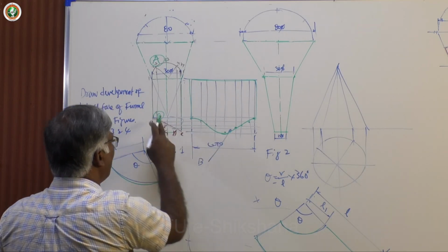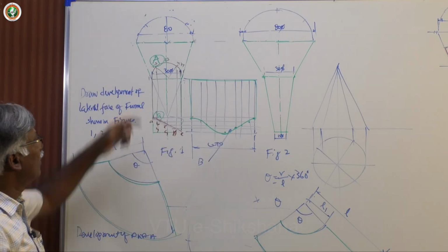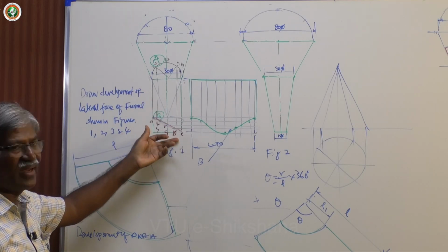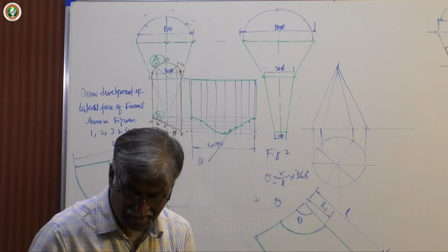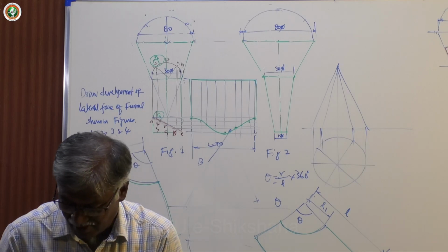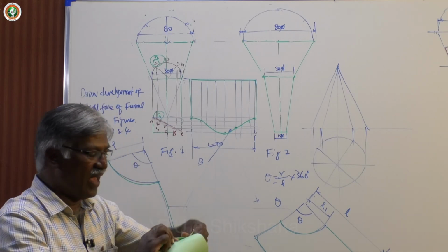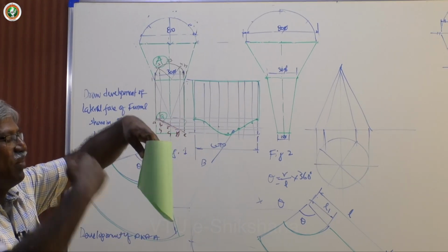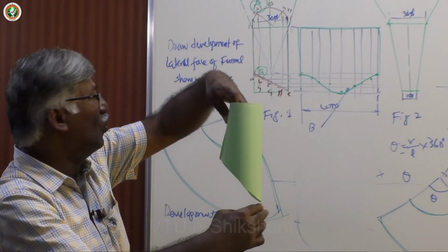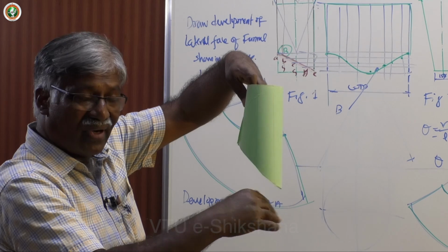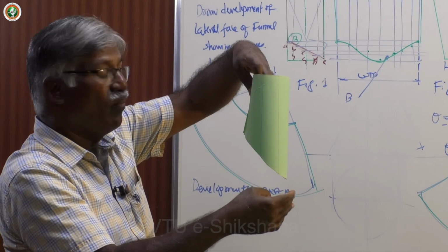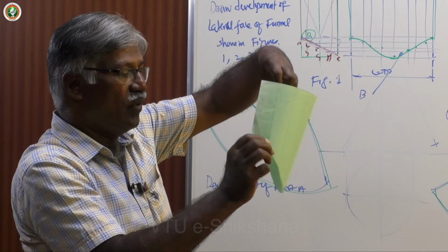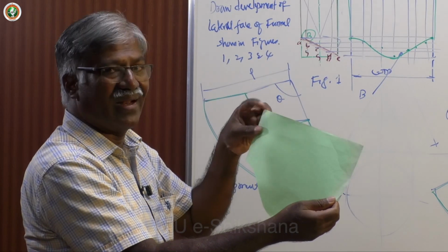So this is the development of part B. Part A, part B. So the simple one is just a cylinder. Here, a truncated cylinder. So here is the development with a particular given angle. Suppose that I take the section plane passing through the right bottom point of the cylinder and inclined at some angle. Now if you open it, you will get like this.